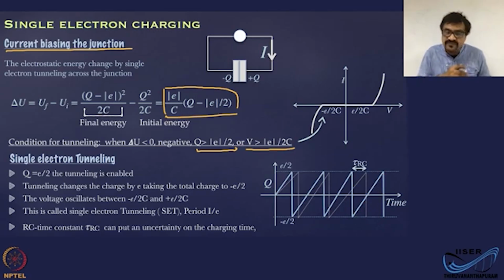And this is going to repeat. So, you have a charging process, then discharge, 1 electron. Charging process, discharge, 1 electron. That is going to happen one by one. So these are single electron charging processes, because you now have a small junction with a very small capacitance which enforces the voltage requirement given by this, E by 2C.